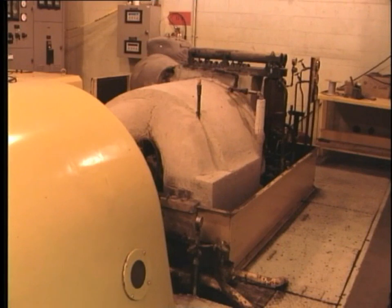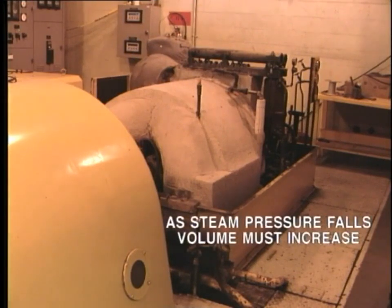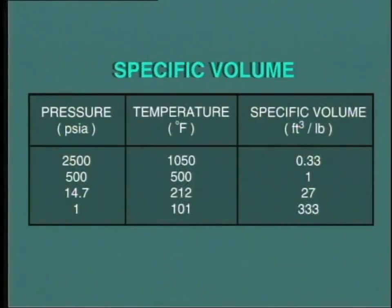This problem of specific volume is of concern to us when we consider the steam passing through the turbine. We know that the steam pressure falls, and consequently its volume must increase as it approaches the low pressure end. In fact, the change in specific volume of steam is quite dramatic, as we can see in this table.